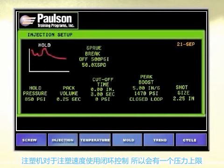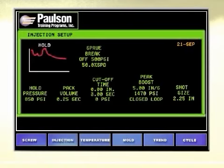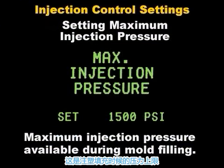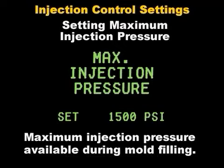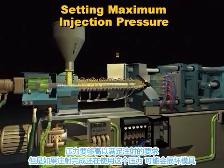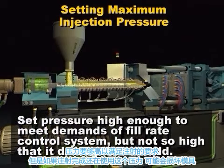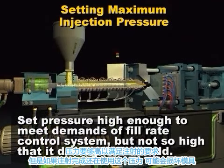Molding machines that use a closed-loop fill rate control will have a maximum or limiting injection pressure setting. This is the maximum injection pressure available when the fill rate control system operates during mold filling. The general rule for setting this pressure is to set it high enough to meet the pressure demands of the fill rate control system, but not so high that the mold could be damaged if this pressure remains on after the mold is full.